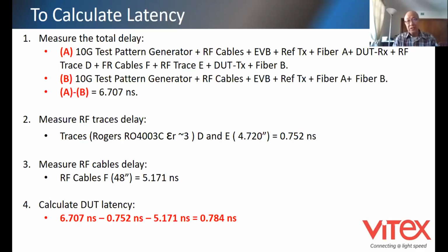So yes, but I would think PAM4 is a little bit harder to measure because the jitters are much more. Yeah. But I think by following the technique to measure the PAM4 eye, you should be able to find your rise time edge. Yes, at the 50% points. Let me see. There are no more questions.